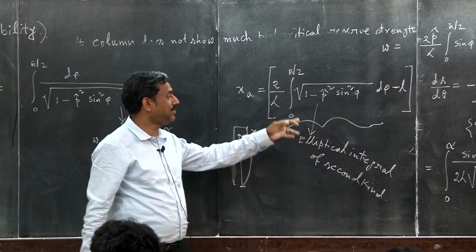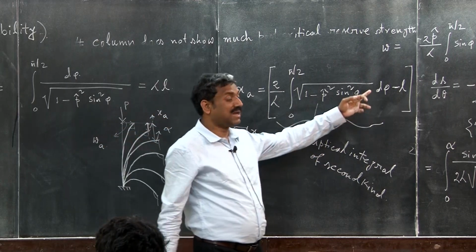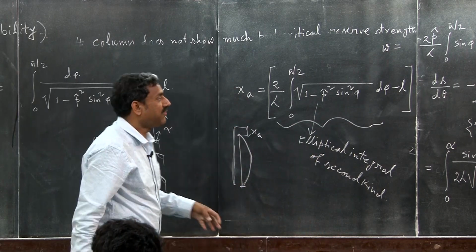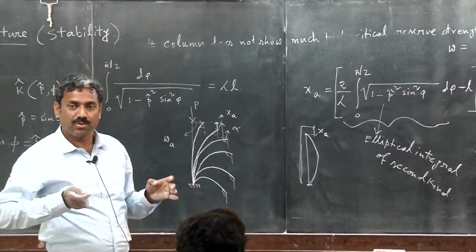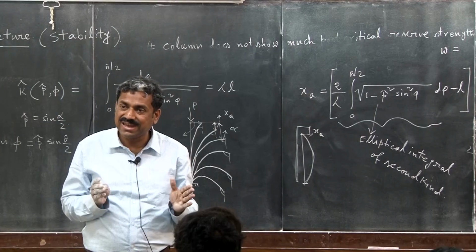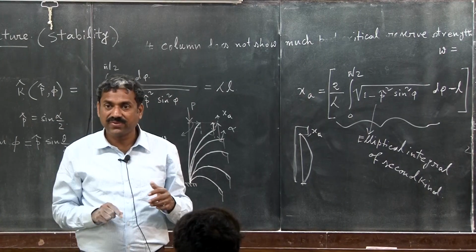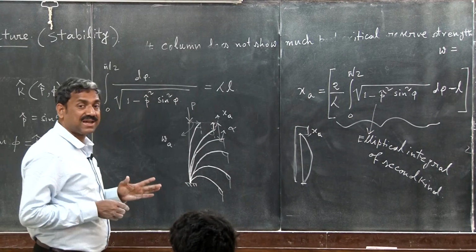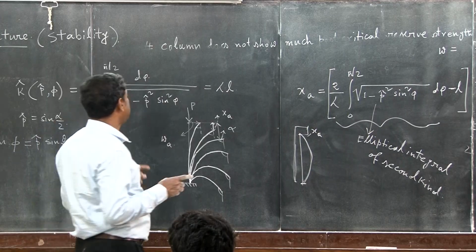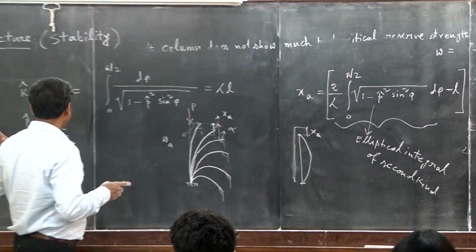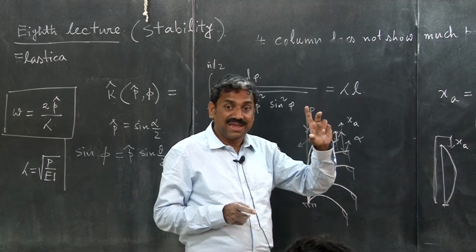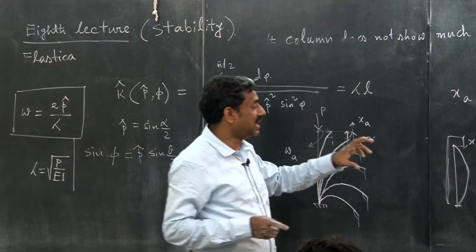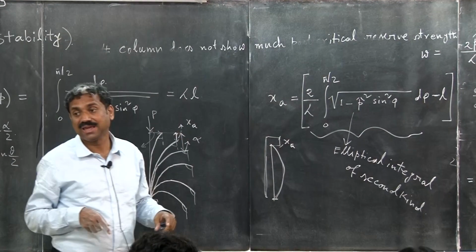Phi is the modular angle, P cap is the eccentricity, and L is the initial length. So, you can find out the level of axial force that the Elastica can carry for a given level of alpha deformation. Next you can find out the lateral deflection W as a function of alpha. Also you can find out the compression in the deformation along the axis direction.